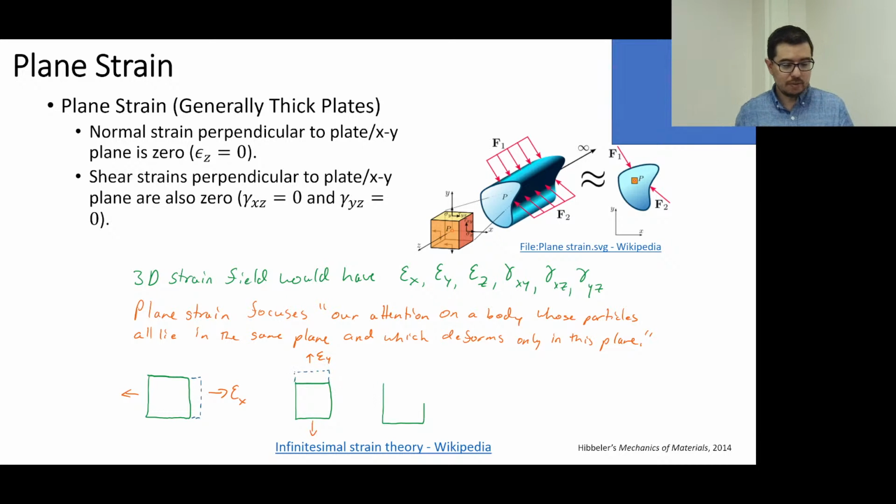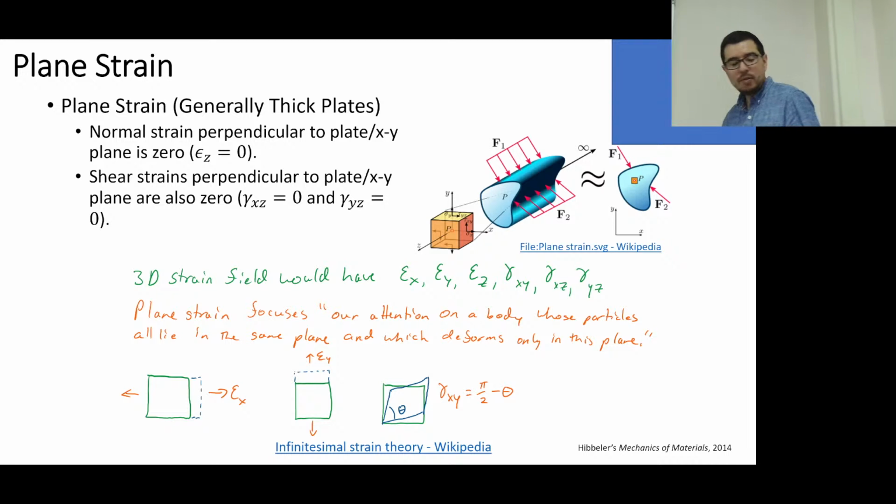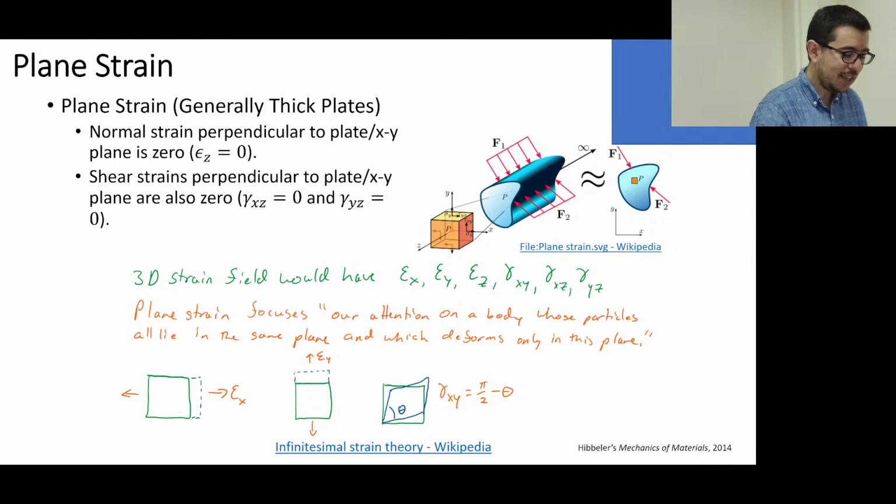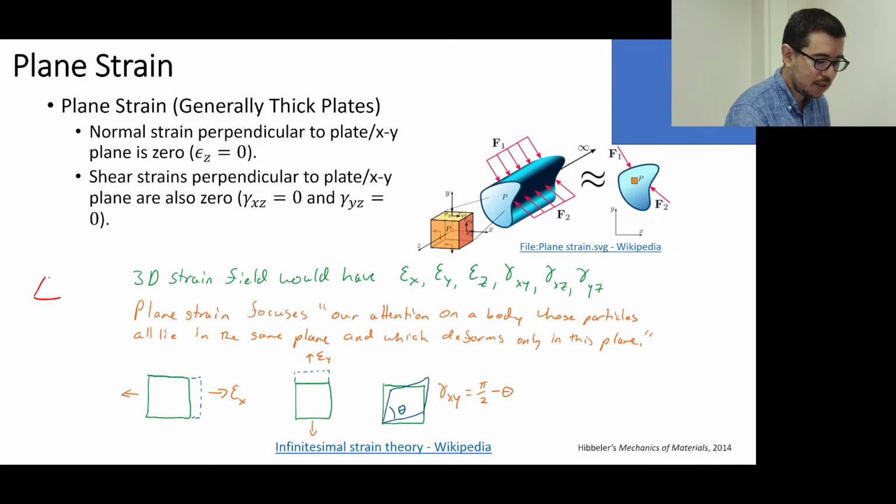And if we have a gamma xy, remember, we said before that you can think of a shear stress causing a shear strain. It causes the element to deform like this. We said this is going to be some delta here, and this is some dy, and the angle in here is the angle we care about.